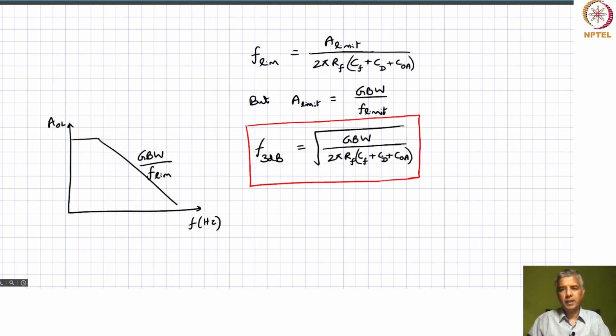Let's say you can reduce the diode capacitance by having a larger bias across the diode. As you increase your reverse bias voltage, you would typically find that this capacitance, the ability to store charges within that diode, actually reduces as you go to larger reverse bias. So the capacitance value could be reduced because of that. Let's look at some realistic values for all these different things.